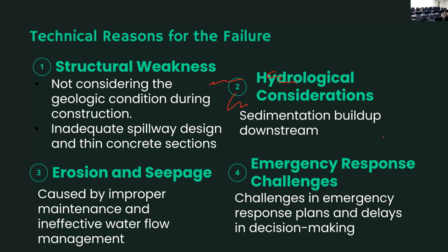Also, due to poor maintenance, the first damage that happened in the main spillway was that the slab washed away. It happened because the joints of the slabs in the main spillway were not thoroughly inspected and taken care of. As a result, a void formed, and when the water rushed down from upstream, it went down through that gap, and eventually there was an uplift pressure which flew the slab away. And once one slab was out, there was just a chain reaction.